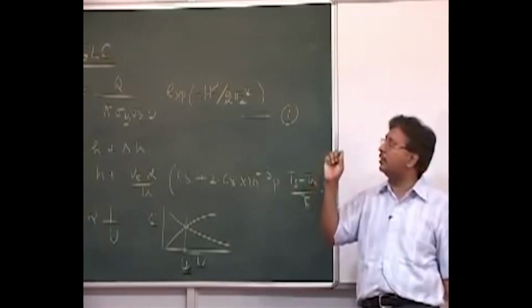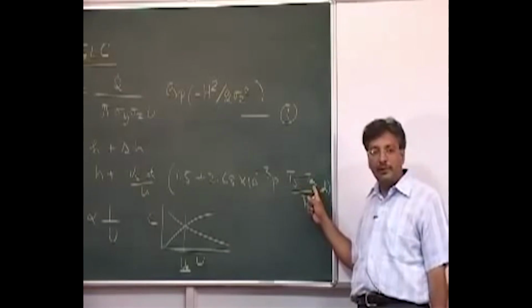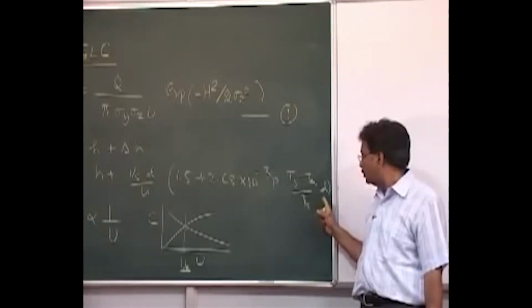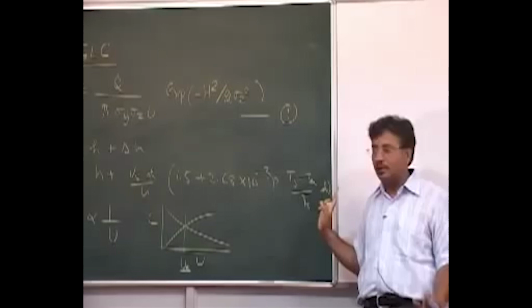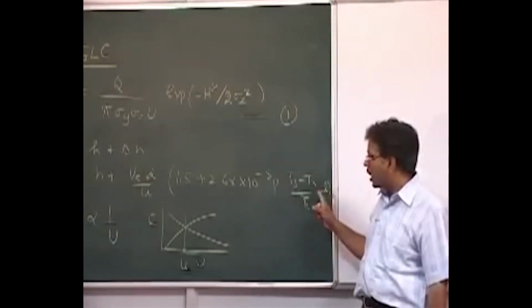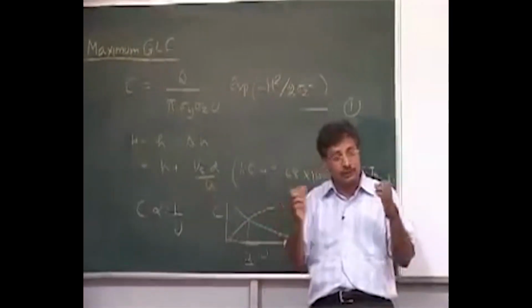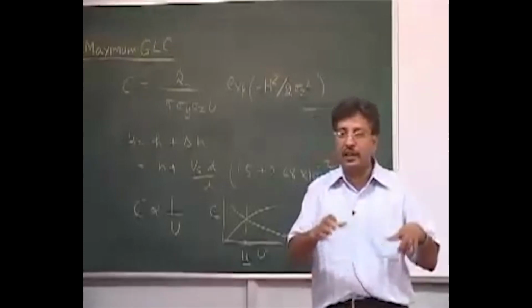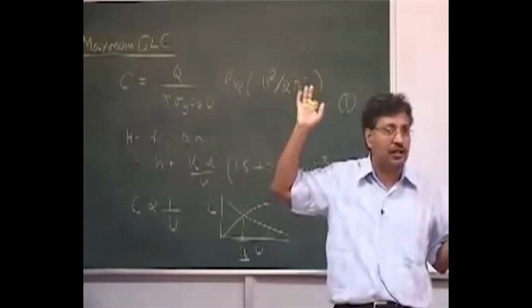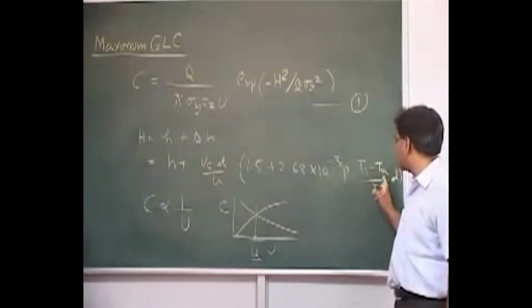They know that the temperature of the exit gases will be 100 degrees Celsius. TA could be variable. This diameter is fixed because they have designed the chimney already. So this TA can be variable, this is fixed, and Vs, the exit velocity, is fixed because they have designed their ID fans and FD fans and what velocity they are going to push the gases out with. So this is fixed. The variables are these.